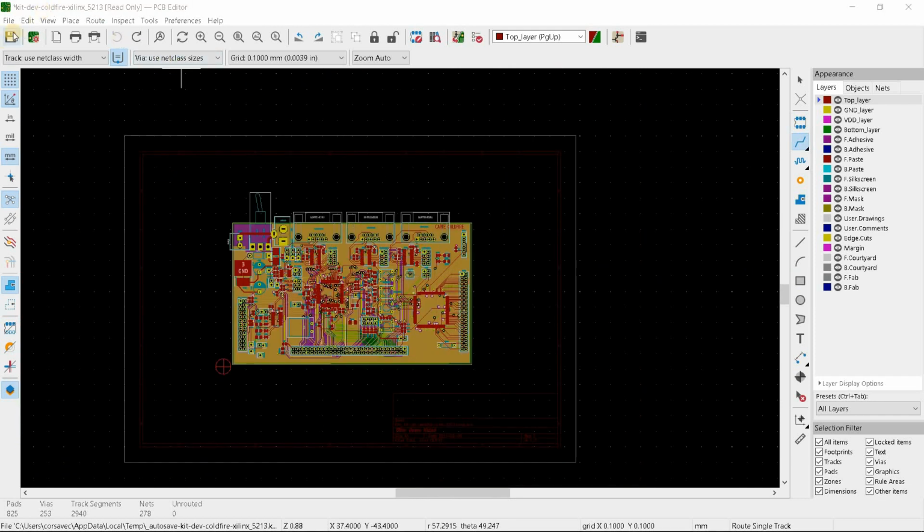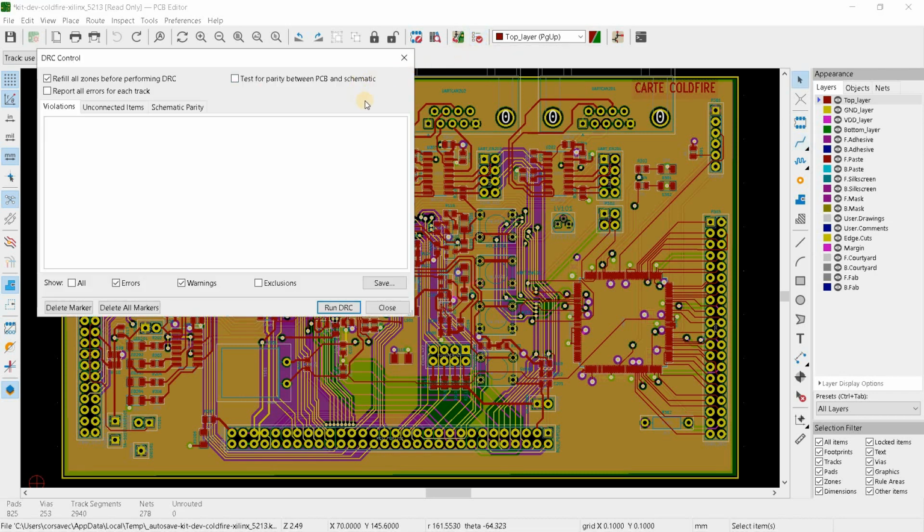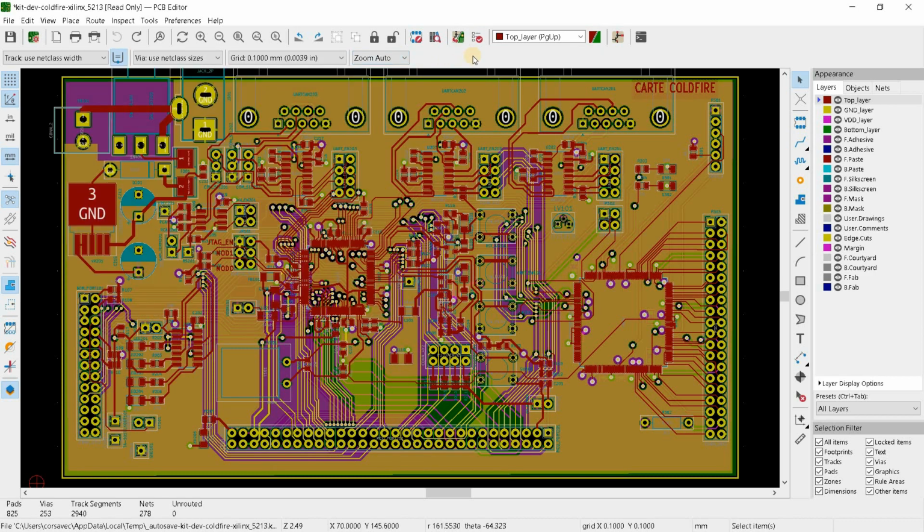Now let's go to the top toolbar. Here, the Scale by Components has been added. Tools for working with a selected fragment of the board have also been added. There are buttons for flipping to a right angle. There are also 4 buttons for grouping and blocking the selected fragment. Nothing else on the top buttons has changed. I don't like that the Show the Design Rules Checker window button now has a new icon. I liked the ladybug icon better.